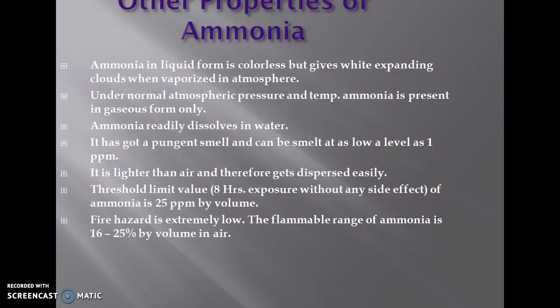These are some properties of ammonia. It is a colorless gas. The boiling point, as you see, is -33 at 1 atmosphere, so you can always find ammonia in gaseous form. A very good quality of ammonia is that it is readily dissolvable or absorbable in water. So if a leak occurs, water would be the best readily available substance which can arrest ammonia. As for fire hazards, it catches fire in the 16 to 25% range.